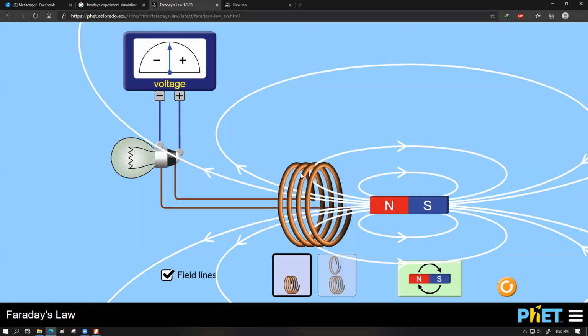So what Lenz's law tells us is that whenever this movement of the magnet is done, it will cause the EMF to be generated within the coil, and the EMF will always be generated in such a way that this motion of the magnet will be opposed. Get this point straight. This is a bit like elasticity. If we have a rubber specimen and you try to extend it, it will try to pull itself back. If you try to push it, it will try to push itself out. So it will always try to resist that deformation.